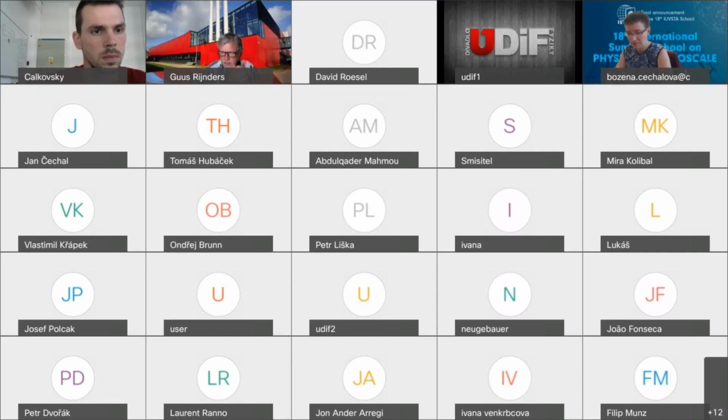I think growth speed is not the issue. One of the major issues is particles, because of this very explosive ablation. If you do not have the right target material, you can easily create particles. And that is what companies like Solmates are really doing to get rid of these particles. Also, as the previous speaker always mentioned, you should have only a few added particles over this complete wafer. And actually, they made very nice progress in getting rid of the particles with PLD already. So that's the problem.